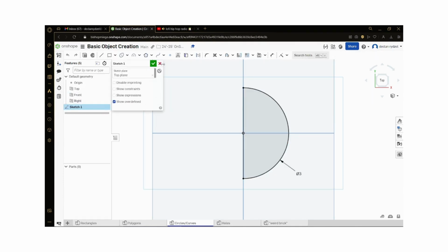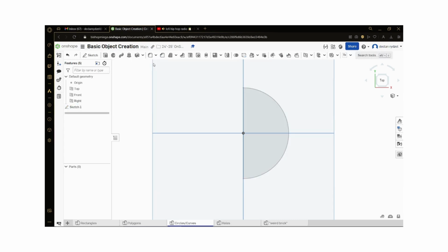There's another way to create a half circle, which is, I think, the easier way, which is going to 3-point arc, and we click 1 point, 2 points, and then we click a 3rd point somewhere out here. So I click there. Now that's there. Then all we'd have to do is put another line here, and there we go. Half circle. So check that.